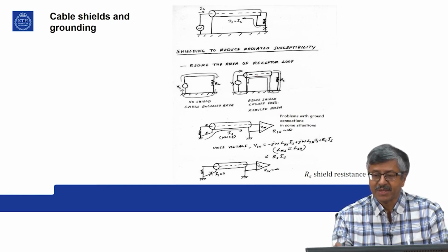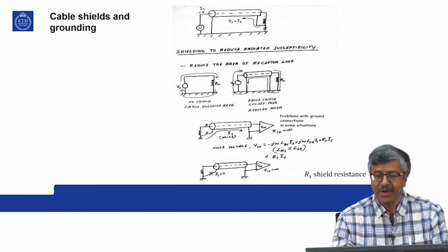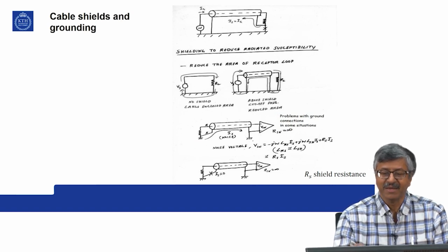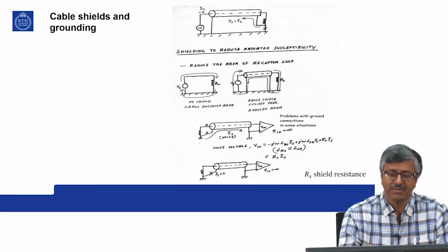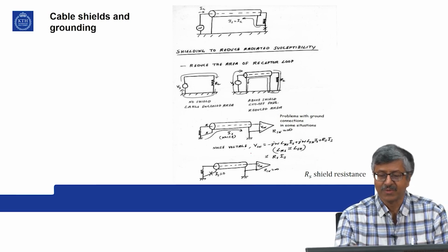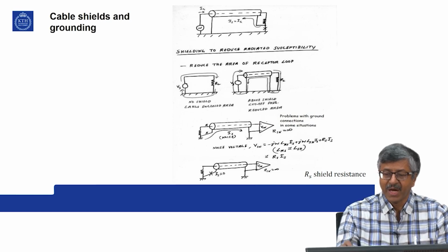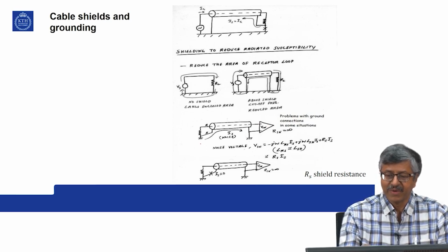But sometimes if you have connection at both ends, it can create some problems. So, you cannot do the connection mechanically, without thinking on both sides. One case is illustrated here. Suppose you have an amplifier or something where some signal is fed using a shielded cable.